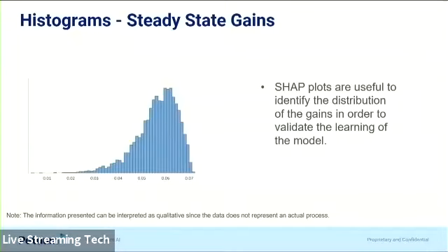And in the same way, we can run the system for all of the history of the operation to find that gain that we saw. What is the distribution of that gain? Where do we typically operate the plant? And in this way, by looking at this, you can say, hey, yes, even though the gain changes, it never changes sign, right? If it changes sign, then that's something to be worried about, because now your action is going to be the reverse. You don't want that. So that's another way to make it even more explainable.